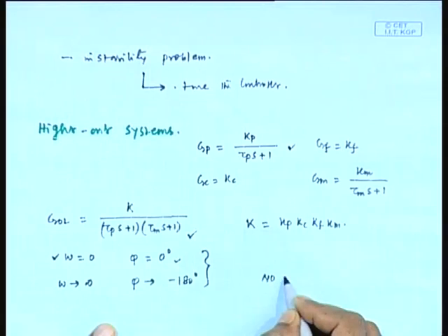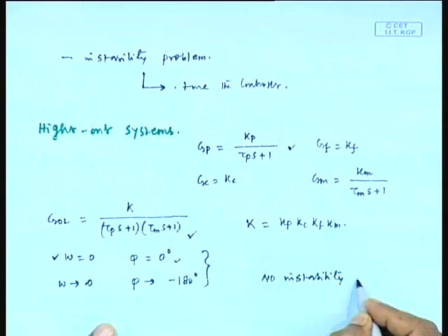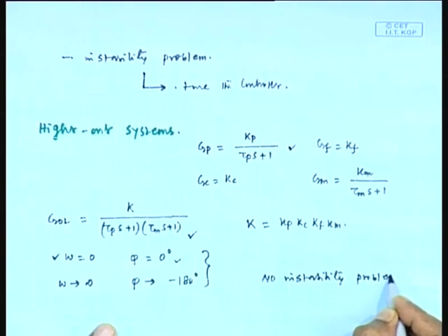That means there is no instability problem. So, see, first order system without dead time, no instability problem. Second order system without dead time, no instability problem.